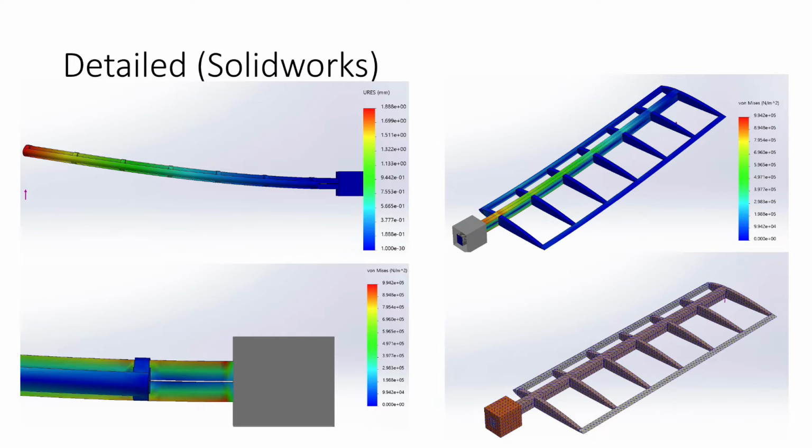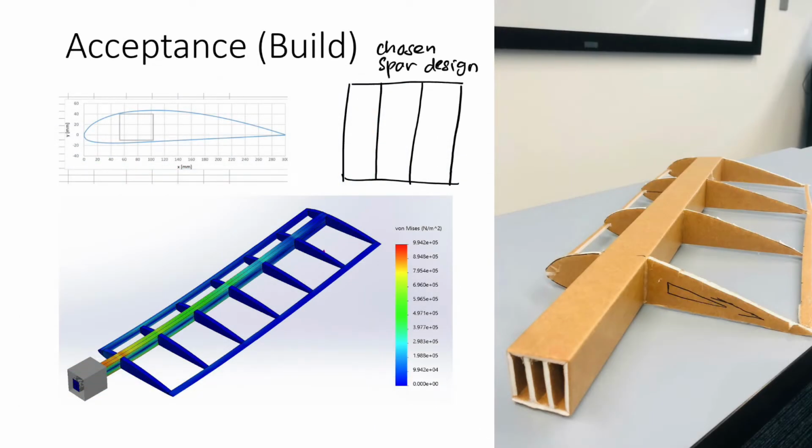One thing to note about our tests is that von Mises stresses were used, which only showed the stress magnitude and not the nature, i.e. tension or compression. Therefore, there was some interpretation of results, but our real-world testing revealed that the foam spar failed first in compression. From the simulations, we used the results to design and conduct real-world tests to confirm our results.